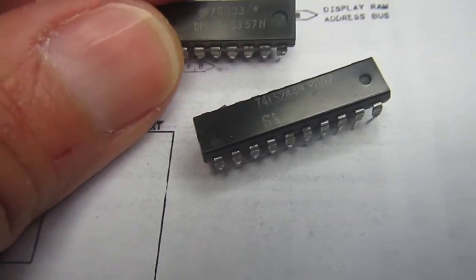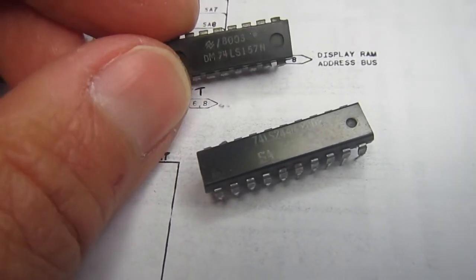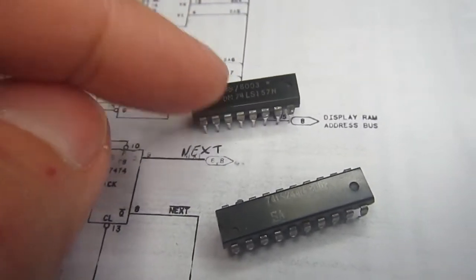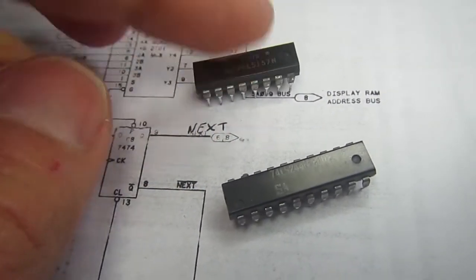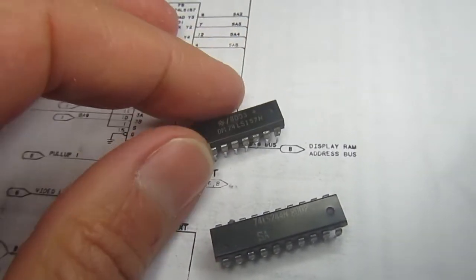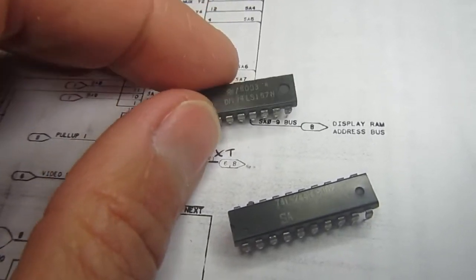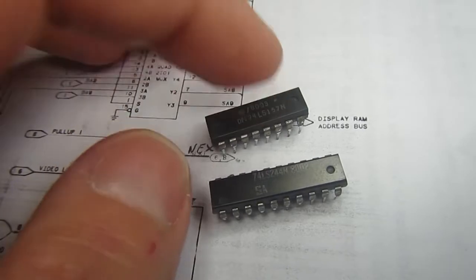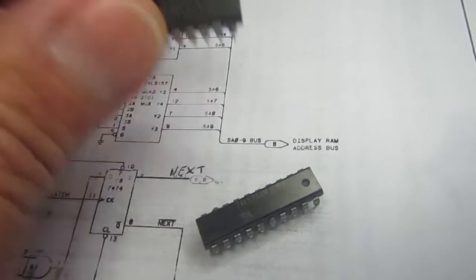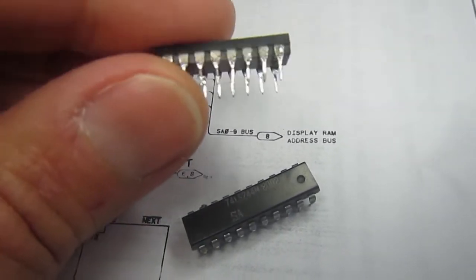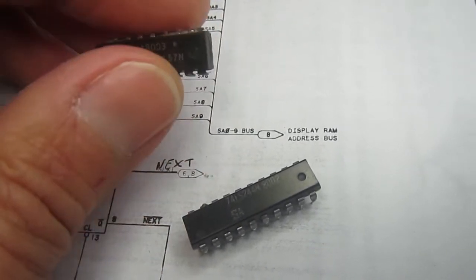According to the data sheet, a high level voltage should never go below 2.7 volts, and this one was going below 1 volt, which was still recognized as a logic 1 by the other chips connected to the output of this one, but really this one must be changed because that pin driver can go bad anytime.